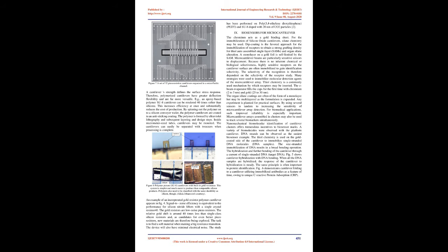Advanced mechanical devices with measurements of micrometers and embedded components cannot be made utilizing fine mechanics. Instead, methods focused on clean rooms are used, in which a three-dimensional etching of a thin silicon wafer creates the cantilevers. Depositing the silicon nitride compounds with low-pressure chemical vapor deposition. Specific geometries and configurations of cantilever structures are readily created and can be combined with liquid handling networks.